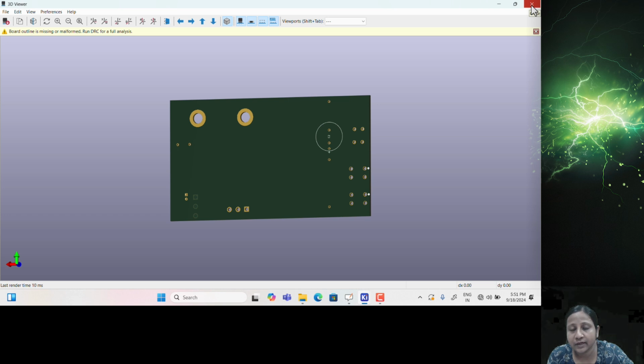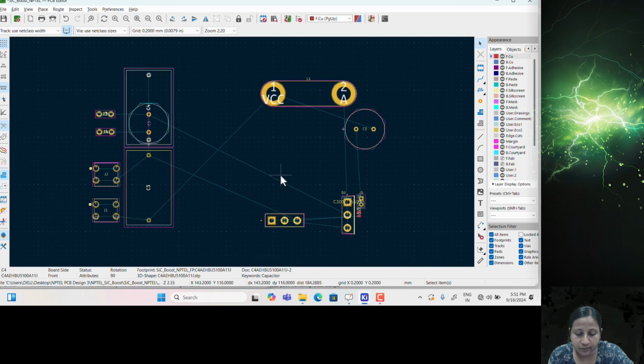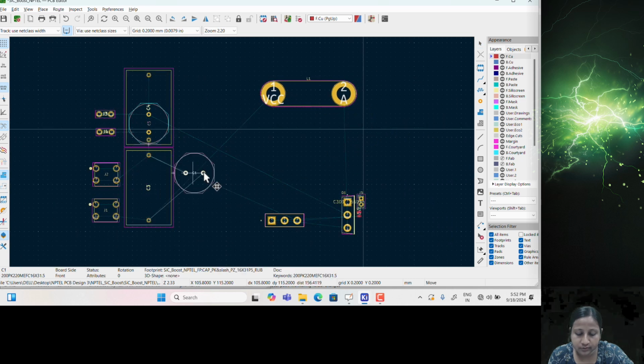Components may have a layout or circle with a bit more area than that of the pins, so you need to check that the pins are not overlapping each other. You can check that after putting all the components.